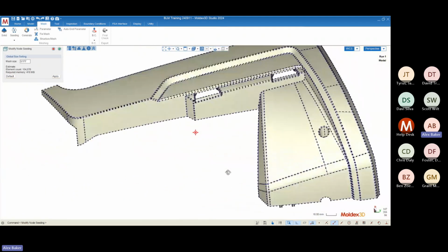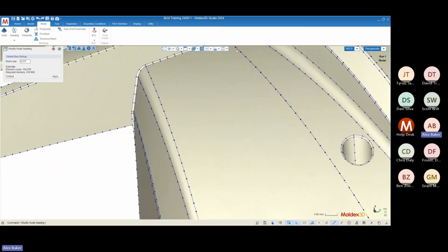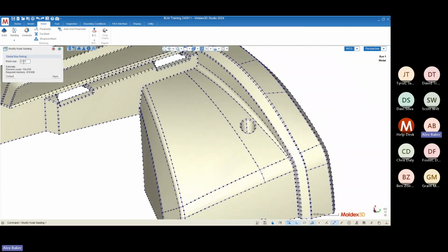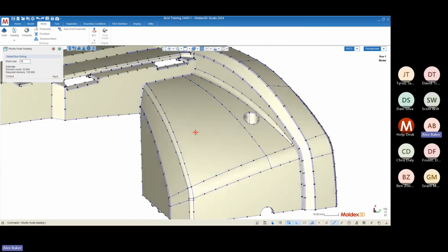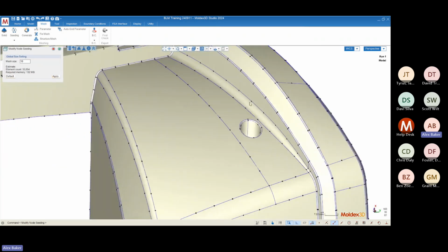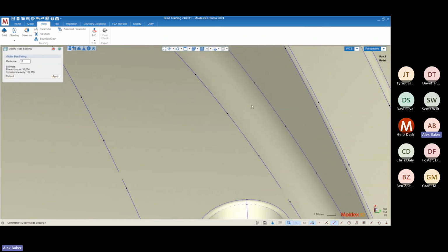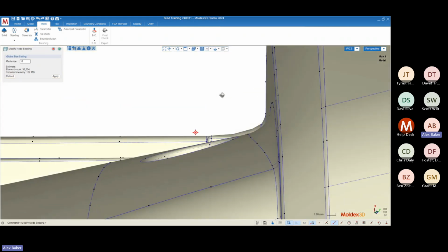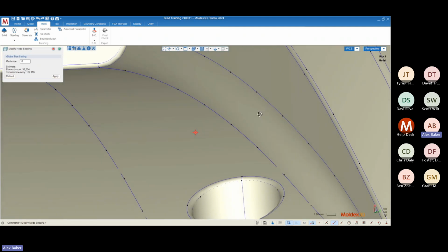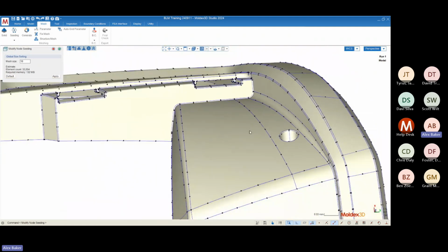This carries into some of the more generic features on our geometry, especially as we increase unreasonably, let's say even up to a mesh size of 10. You can start to see how some of these geometries, like this big fillet here, are just going to have an element that goes from here to here, and it ignores that fillet contour completely.